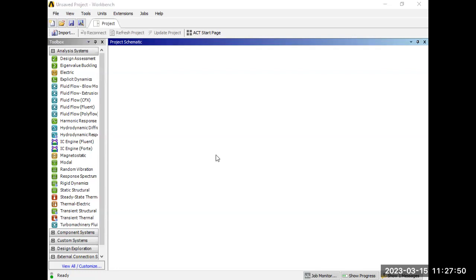In today's class, we'll try to understand how CFD works. The working of CFD is that we will take one aerofoil, NACA 4412. You can select any number of aerofoil series, and then we'll import the coordinates of the aerofoil to the Workbench, and first design the model. After designing the model, we will apply the boundary conditions, and then simulate the model.